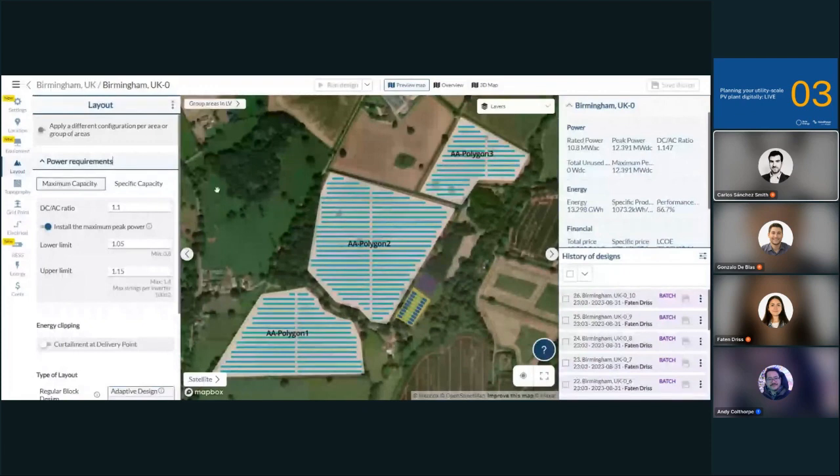Yes, of course, Peyton. So what I normally do is consider between 1.05 and 1.15 on DC-AC ratio when using bifacial panels. It is true that on monofacial designs, this can be adjusted up to 1.4, but I think that for bifacial, the extra energy generated from the backside of the panels could lead to increased clipping during peak load hours, especially during summer.